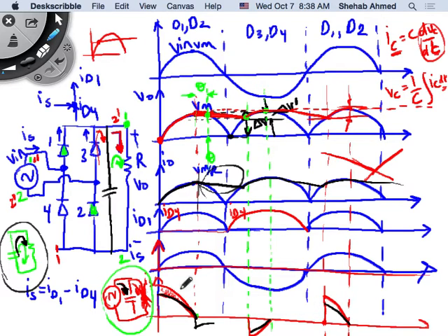When the capacitor is being charged, the polarity of the current is not changed. It's always into the capacitor, right? My supply current had to flip because diodes 3 and 4 were now conducting to charge the capacitor. So this black has to be on top. We agree that this was wrong. This black has to be flipped because the capacitor current is in the same direction when it's being charged, always into the capacitor. That's why this is fine, this is fine. I messed up on this one because I drew it on the supply current.